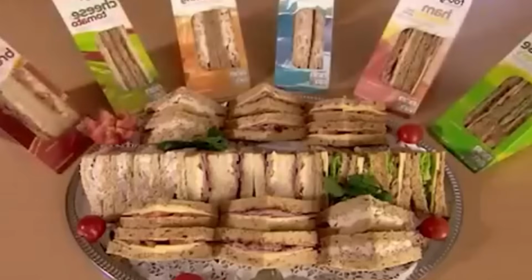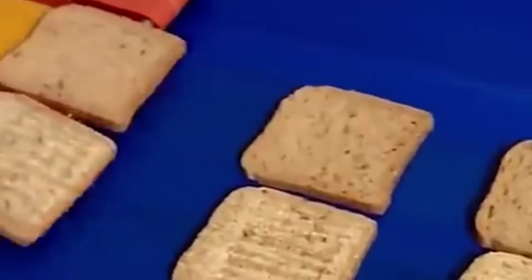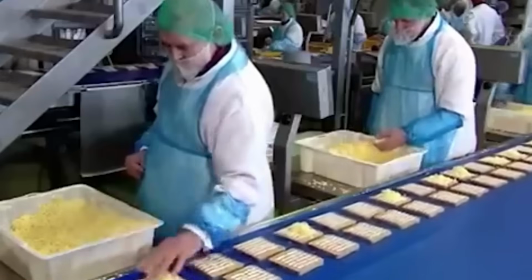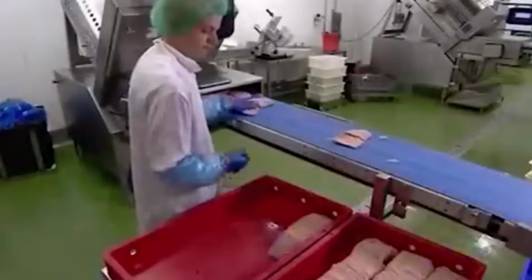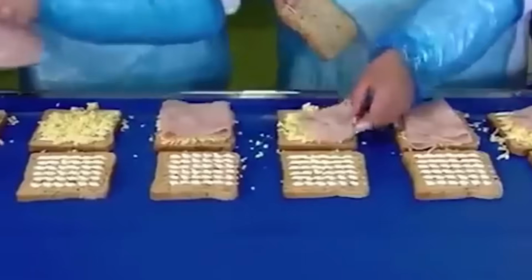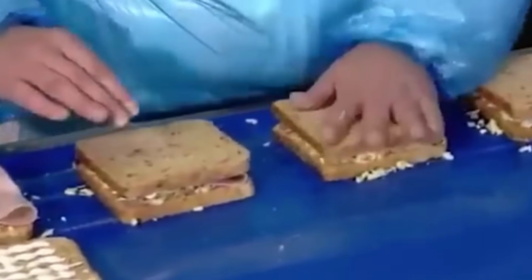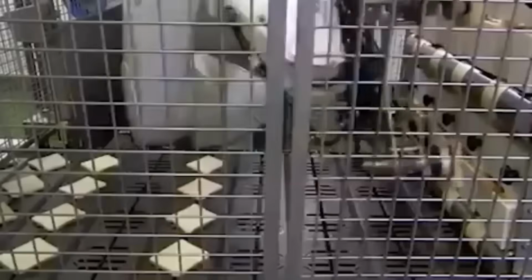At this stage, the sandwich enters the compression and forming section. A series of soft rollers or belt presses applies uniform downward pressure to stabilize the build, enhance bite adhesion, and ensure the sandwich holds together through slicing, wrapping, and handling. The compression rollers are timed precisely to match belt speed, and the pressure profile is tuned to the product type, with more delicate sandwiches receiving lighter contact and denser builds compressed more firmly to lock the layers in place.